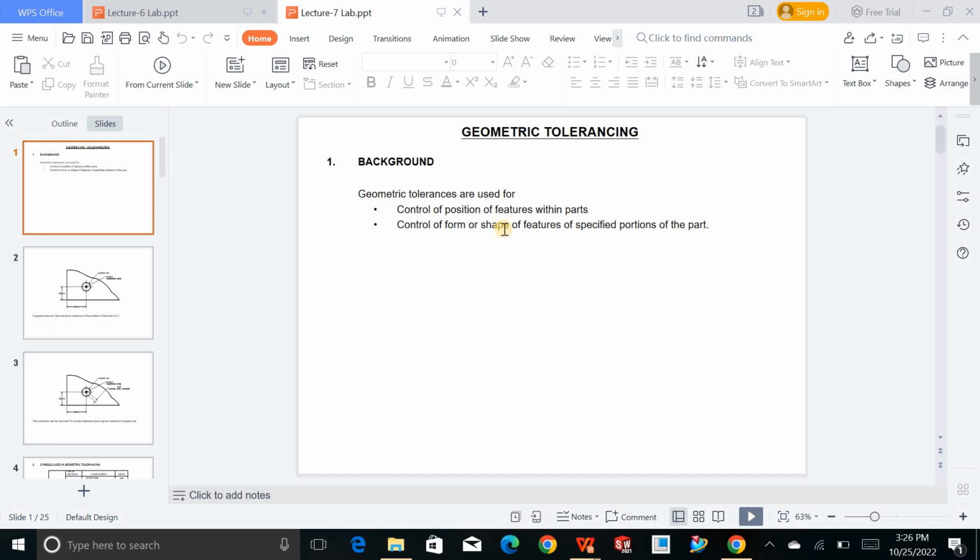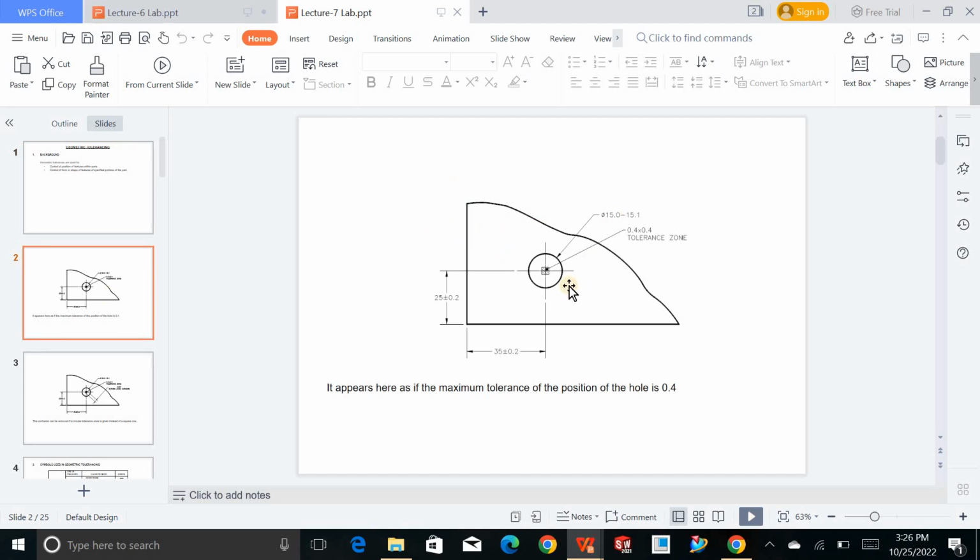Sometimes certain industries have very limited tolerance, or they even skip the tolerance. They don't have any tolerance in the case of aviation and precision industries, right? So we have this object, as you can see the diameter is given, and you can see over here the distance part. This is the bilateral tolerance. You can have positive and negative, lower or higher by 0.2. So this could be 25.2 or 24.8. You can have these examples, right?